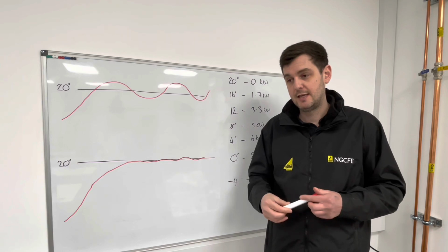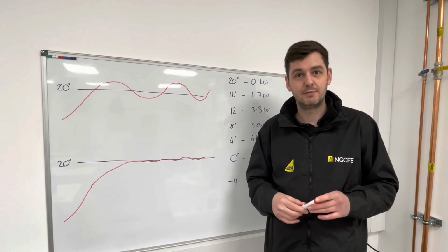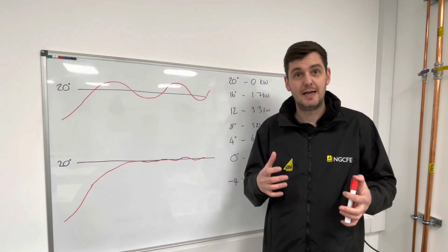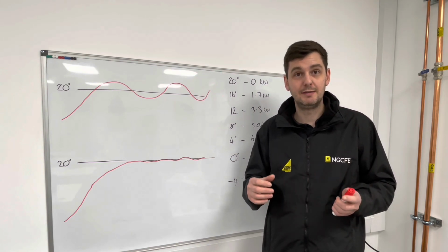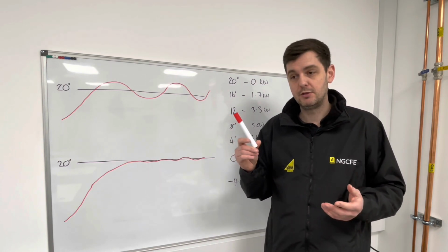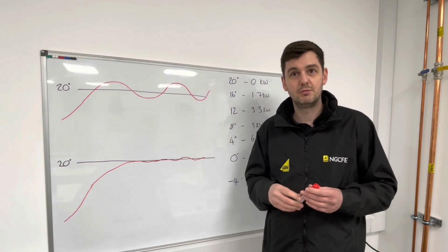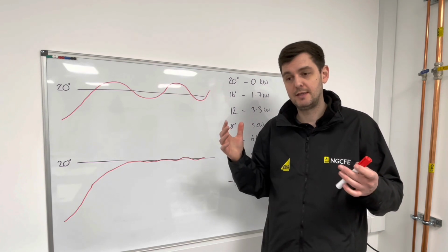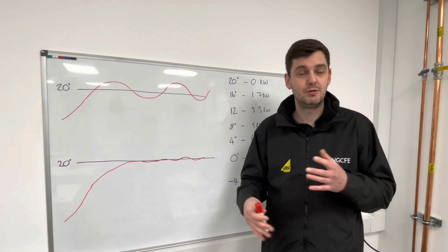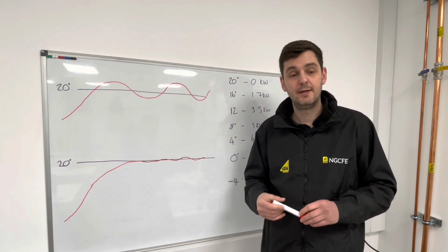If you've got a more modern property, with not cavity walls, stud walls and floors that don't have a lot to them in terms of mass, so they heat up quickly and they can lose heat quickly, then you would probably not look at maintaining a setback temperature, because ultimately the mass of the property is not going to retain any of the heat. There's no benefit to it. So there's multiple factors that you need to look at, and this is where the engineering design perspective comes in.